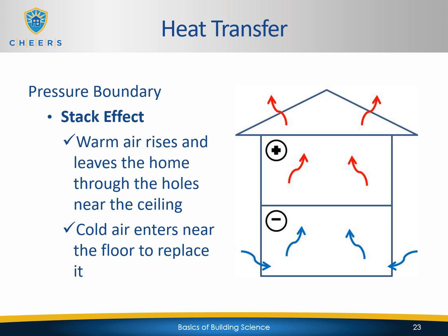Now, given that it's an uncontrolled constant airflow, it's going to create a convection loop within the actual house. As air is heated and rising to the top, it's going to be sucking cold air from the bottom. So it becomes almost a vacuum effect within the home itself that perpetually keeps the convection loop going. Hot air pushes up, sucks cold air from the bottom, and it just keeps going.